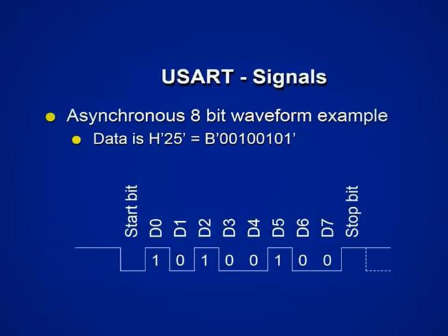By design, this is an inefficient protocol because to send 8 data bits, we need to send one start bit and one stop bit. At the receiving end, start and stop bits are stripped off and only 8 bits are sent to the host computer. Thus, out of 10 bits sent, only 8 bits are used and hence efficiency is about 80% only.